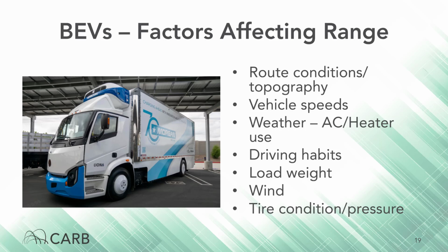Weather and AC heater use affect range. As we discussed earlier, there are optimal temperatures for batteries to charge and retain their charge. Both hot and cold weather can have adverse effects on the range a battery can provide. Cold weather, because unlike conventional vehicles that use heat produced by the engine to heat the cabin, heaters in BEVs are electric and draw from the battery. The same is true for hot weather conditions. The AC draws its power from the battery as well to cool the cabin, in addition to the battery itself.